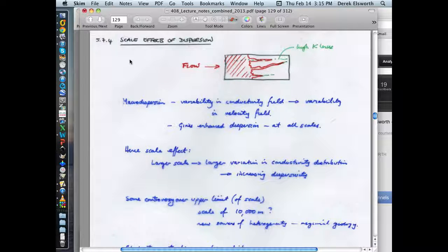individually within the pore structure, we might have flow velocities occurring between grains where it's slow at the edges, at the pore throat edges, large in the middle. And so you'd expect this to give a high velocity in the middle, which should carry stuff downstream quickly, and less velocity at the edges, which would leave it not traveling very far, and there'd be some spreading that would occur with this.